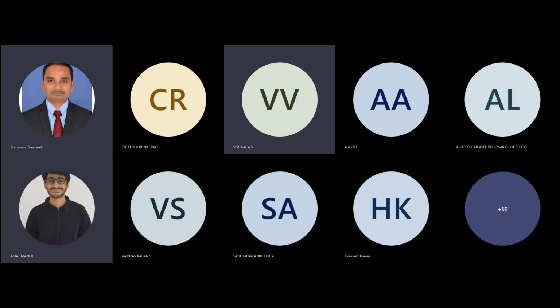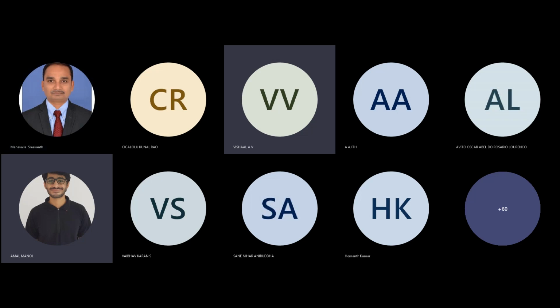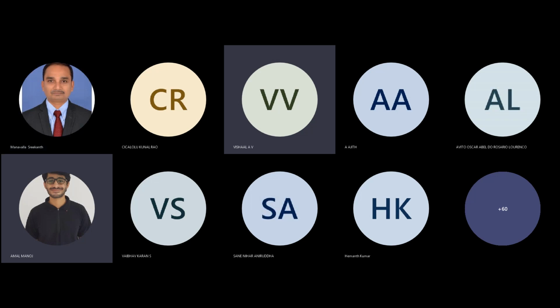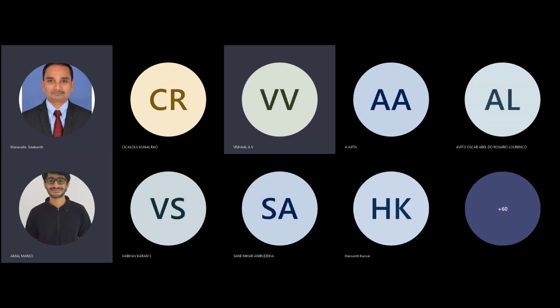Most of the time, when the temperatures are below 500 degrees Celsius, the net heat radiated is smaller than the amount of heat conducted or convected. So in such cases, we neglect radiation because it is lesser in quantity, and also you will see from the mathematical equation of the radiation law that radiation is mathematically difficult to deal with.